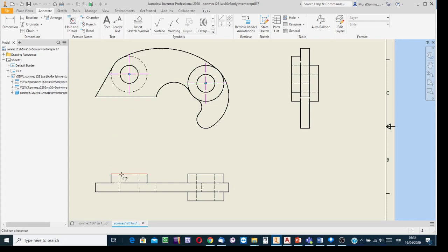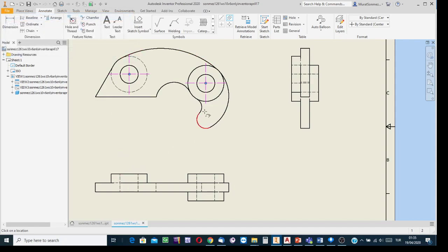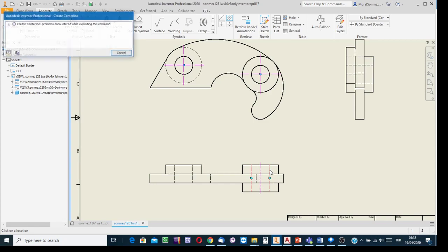On the top view, to say that this rectangle is the image of a revolved feature, there is a hole over here, it's a revolved feature, indicate the surface limit lines, and between them the program will create the axis of symmetry. Here there is a notice, I don't know why Inventor notified me. Click on this, indicate this limiting line, indicate that limiting line.